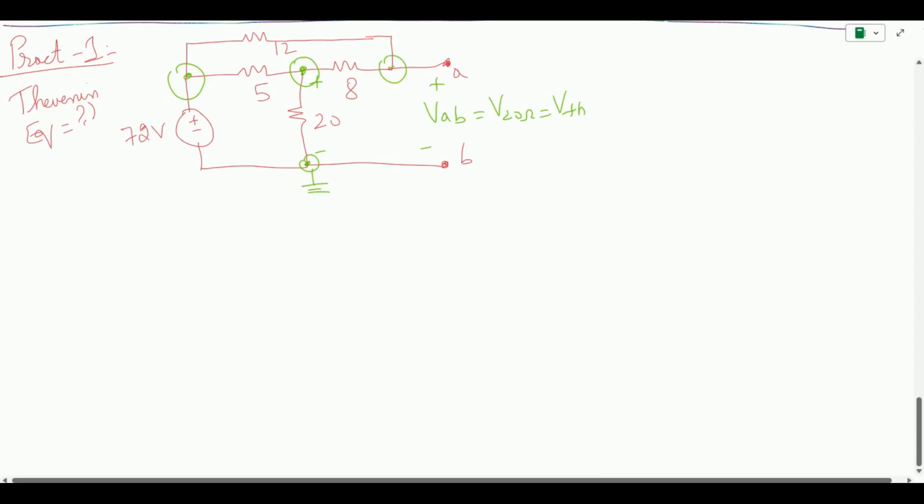So then you can figure out the voltages at essential node, let's say A, B, C, and D is a ground node. So you have basically 4 essential nodes, so you will get 3 equations, and you might come across a special case of node voltage and the equation might reduce to 2 equations. So then you can figure out what is the voltage appearing, let us say at VB.